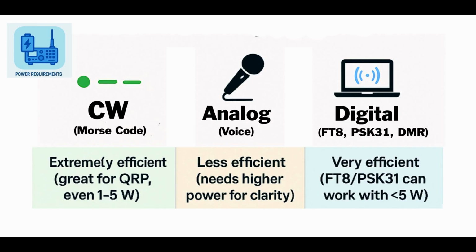The power of a transmitted signal is spread across its bandwidth. If two signals have the same total power but different bandwidths, the narrower bandwidth signal has more concentrated power per hertz and a higher power density, making it easier to detect in weak signal conditions. The wider bandwidth signal spreads the same power over more frequencies and has a lower power density, making it harder to detect in weak signal conditions.